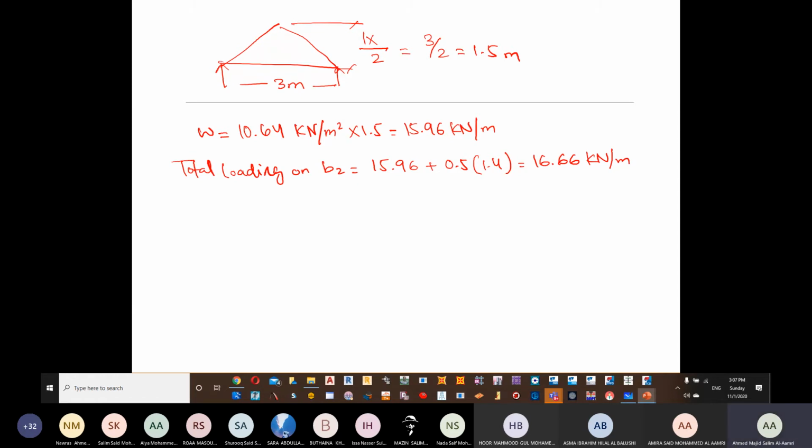Suleiman, it's not necessary. Normally, in most of the design, in most of the software, we only use a rectangular section for the design, unless you want the T section or the flange section to take a certain part of the bending from the slab. Now that can be inputted in the software, but normally we design the sections to be rectangular, although for certain sections T is going to be more economical.